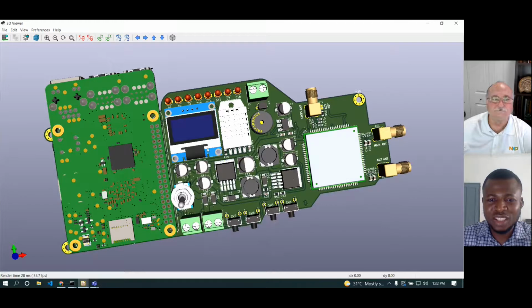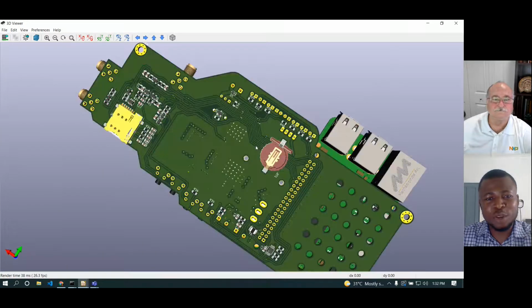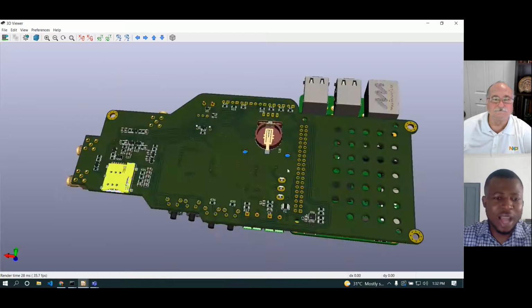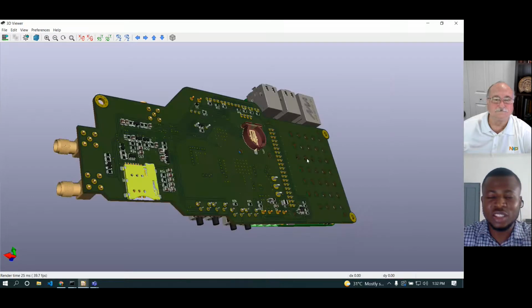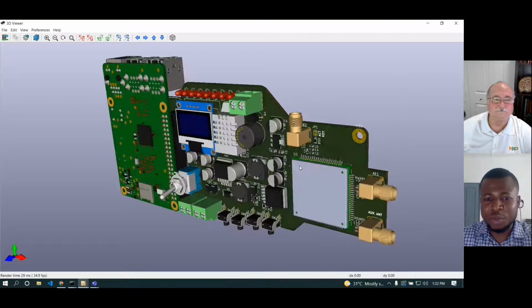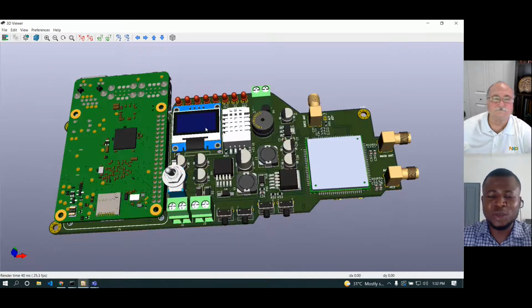So it's a very simple system with a 4G LTE IC from Simcom 7600GH. That's what I'm using this time, and then a Raspberry Pi. Yeah, just that. So this particular system collects all the data from the other IoT sensors and then backs them up on the cloud. So it saves locally, but if there is internet access, then it transmits it to a server in the cloud. So that's what this particular device does.